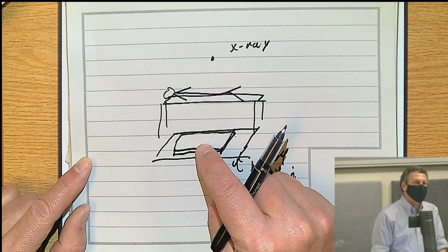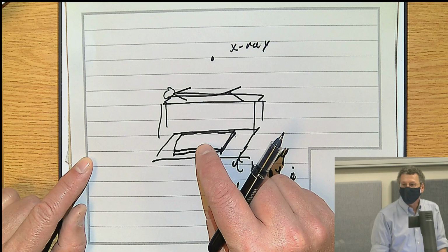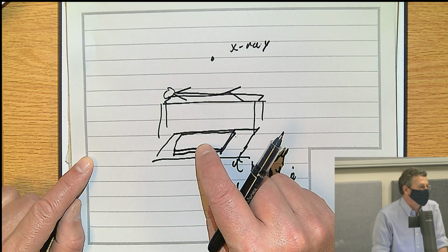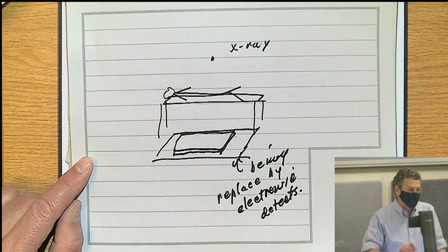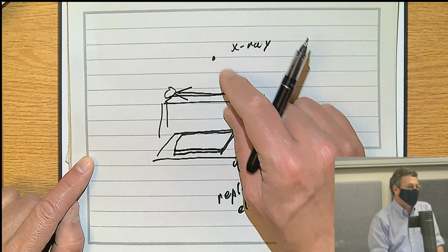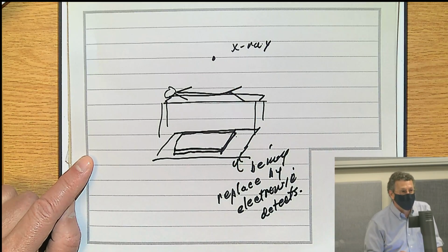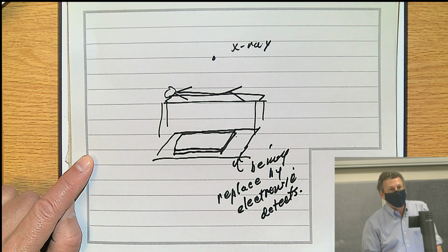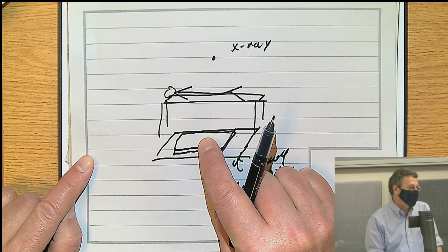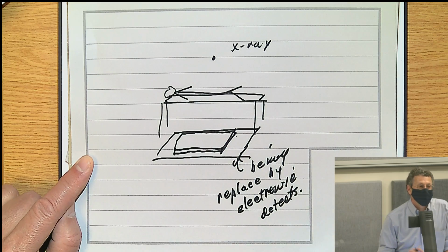So the X-rays hit the scintillating material, and what they do is emit photons at a lower energy. If you were in the room and you turned off the lights, and you had the X-ray source on, and of course you'd want shielding to make sure you're not exposed to the X-rays, you'd see that the actual scintillating material glows, okay? It glows, and that means that the X-ray photons hitting it are being re-emitted in a fluorescing process at a lower energy, which is visible light.